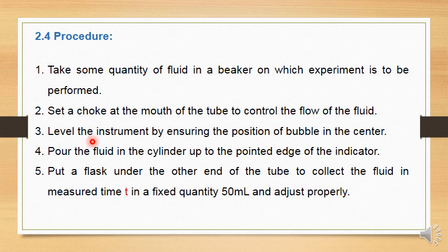Number 3, level the instrument by ensuring the position of the bubble in the center. Leveling of the instrument is very important. The time of flow of water or any liquid from this viscometer can be disturbed if your instrument is not leveled. So you must level your instrument by using the level bubbles, like in swimming, just like that. Just ensure the leveling of the instrument.